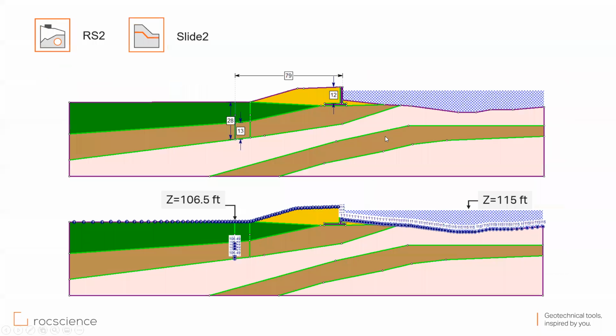For this one, let me tell you the story behind it. We have this levee model. We have a total head of 115 feet here. But when we have this head, there is a pore water pressure in this region, and pore water pressure is always bad. It reduces the factor of safety. It reduces the effective stress. So sometimes, to reduce the pore water pressure, they use something called relief valves. This relief valve has a total head of 106, which is less than this 115, which means that we are reducing the head at this point.